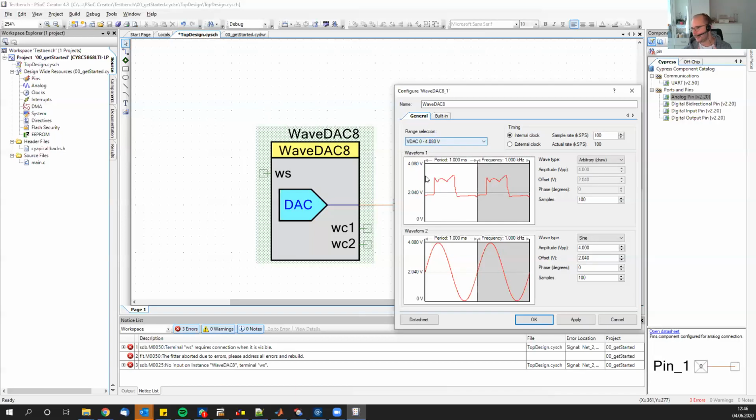If you shrink that down to just a volt, then the slew rate is comparably good, you can make those curves very fast, and later on, for example, use an op-amp to simply amplify that. If you have the full swing, then the slew rate remains the same, so it might be possible that the output is not fast enough to create that signal. So that's the story a little bit in here.